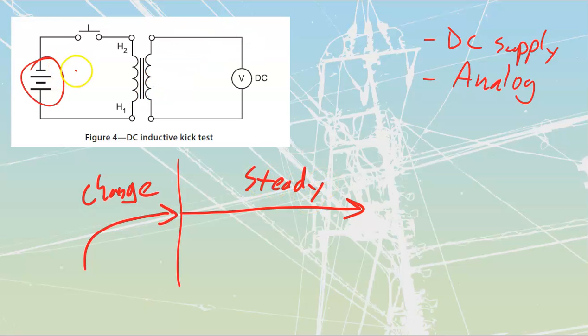Well, how does that affect this side? That means that for a brief instant, when I power this thing up initially, I'm going to have an expanding amount of flux. My lines of flux going around here are going to get larger and larger and push out, coming across to the other side of the transformer, thereby inducing voltage, right? Faraday's law, e = BLv. We've got flux density, conductor length, and velocity, because this thing is moving over here. So we'll generate a value of voltage.